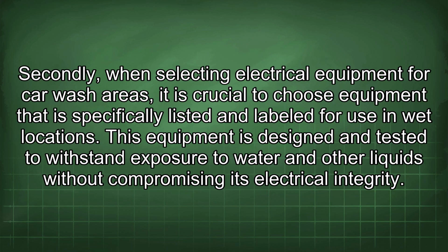Secondly, when selecting electrical equipment for car wash areas, it is crucial to choose equipment that is specifically listed and labeled for use in wet locations. This equipment is designed and tested to withstand exposure to water and other liquids without compromising its electrical integrity.